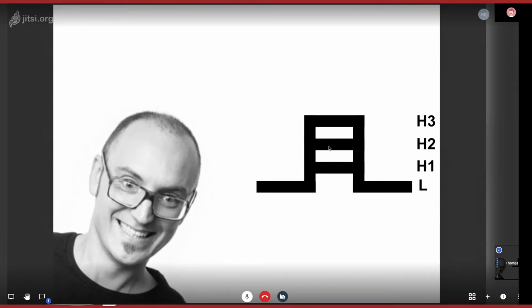When we move on now and look towards 400 gigabit, and look backwards to our initial rectangle shape with the high and low event. So when we now add 2 intermediate events into our rectangle shape, so we have now low, H1, H2, and H3, so we have 4 in total, we can encode basically in one signal 2 bits. So that's pretty helpful. How does this look like?